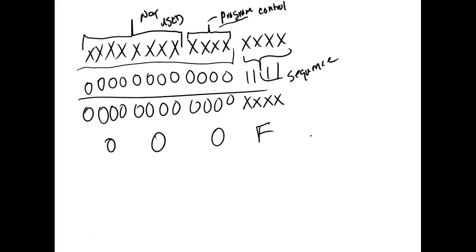Okay, just so I'm clear, if you were only using 3 switches, you do 0, 0, 0, 7. That's exactly right. And we could have used more, but I don't have enough switches up here. I've got 5 push buttons, but one of them is a normally closed push button, and here we don't want to use a normally closed push button. Then I've got 4 switches up here. I was using the 4 switches to set up my sequence, and I was using these 4 push buttons to control the sequence: when I clear, when I don't clear, when I load, when I copy over to my other register.